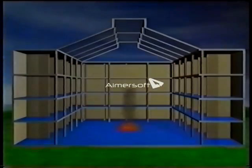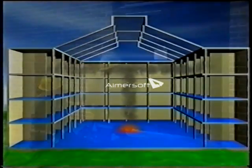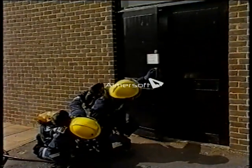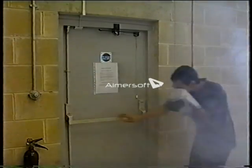Another possibility is that with no means of escape, the gases will cool as they rise, gradually forming a static layer of smoke which may build up, spreading around the building. It should also be remembered that in gaining access to the lower floors, firefighters can inadvertently open up an inlet vent, and this may result in the products of combustion moving around the building. The possibility of accidental venting in this way, or even by well-intentioned members of the public, may result in increased fire growth or even a backdraft.